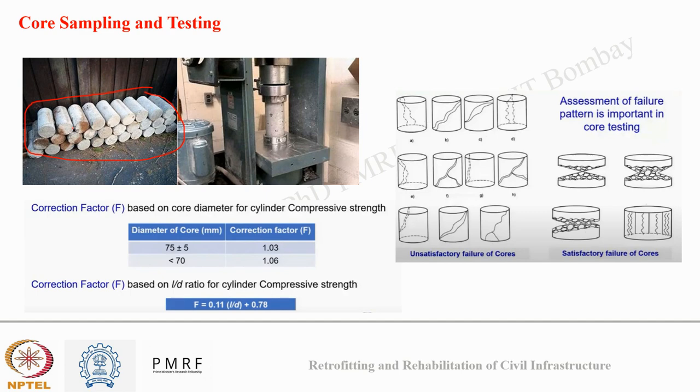Now, post collection, finishing, and storage of concrete, the cores are tested for compressive strength using a compression testing machine, as shown in these images. For carrying out compression testing, the loading rate is fixed. For cylindrical core testing, the loading rate is 14 Newton per millimeter square per minute. Upon reaching the ultimate failure load, the compression testing machine will stop applying the load, and thus, with the known cross-section area of the cylinder and the failure load, we can estimate the compressive strength of the core.